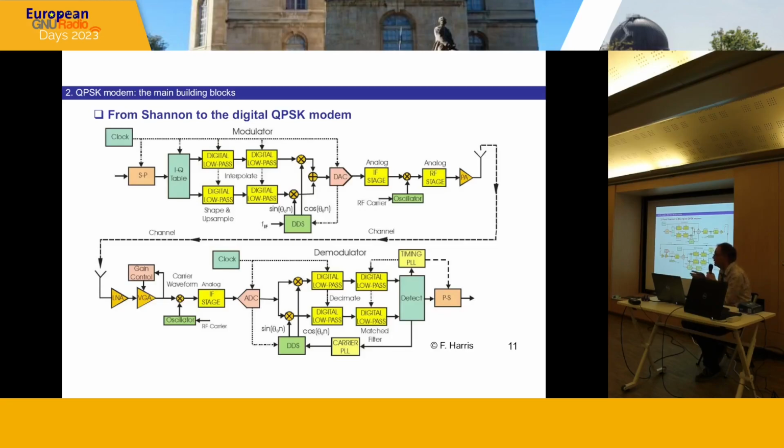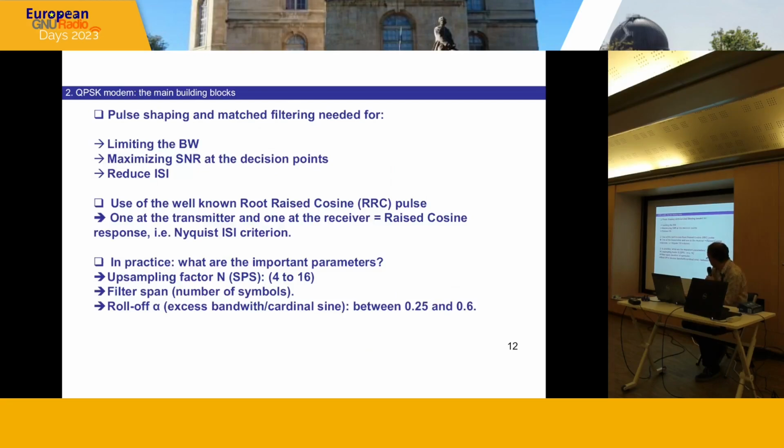When you don't have exactly the same frequency at the transmitter and the receiver side, you will have these problems, and also the problem of the timing that you have to recover, because you're not exactly aligned with the symbols that you are transmitting. So this has to be in your system if you want it to work. So that's the first thing I'm talking about.